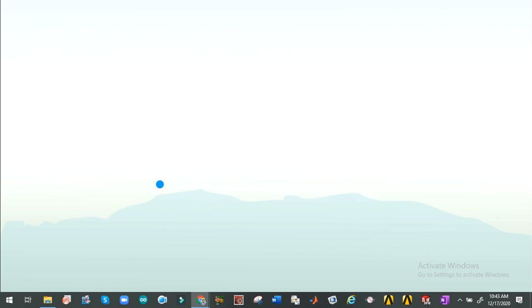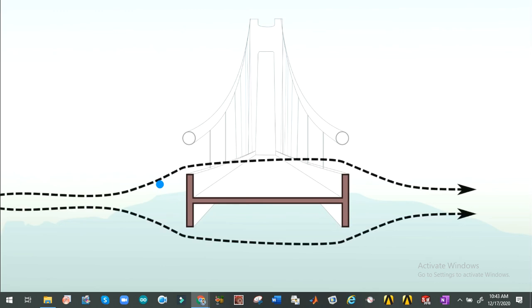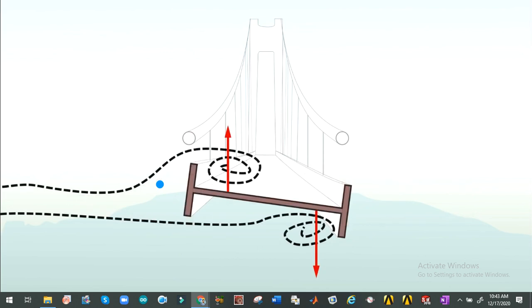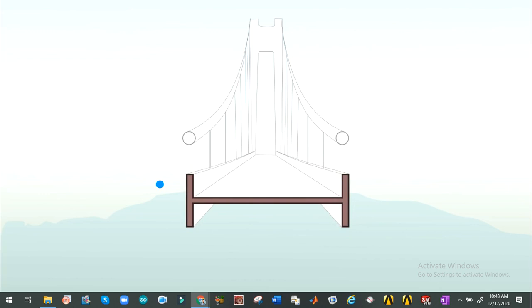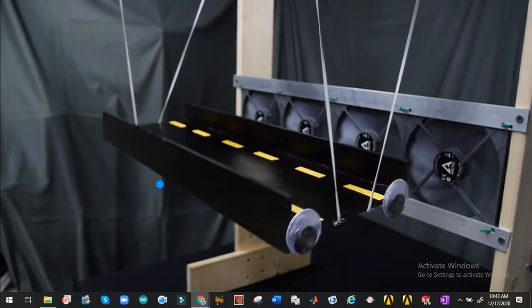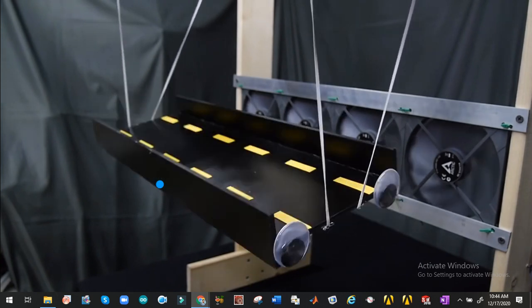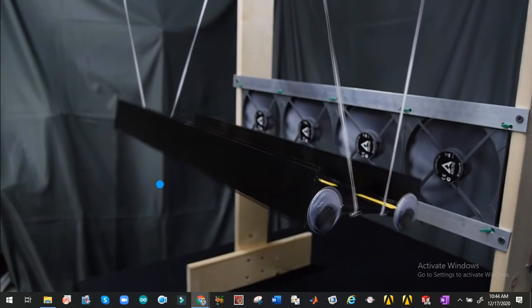Rather than a truss through which wind can flow, the shape of the Tacoma Narrows Bridge, with the large steel plates on either side, created some strange interactions with the wind. Any small amount of twist in the bridge created vortices, or areas of low pressure, in locations that actually amplified the twisting motion. Each time the bridge returned to its natural state, its momentum twisted it in the other direction, where the wind could catch it and continue the cycle. This phenomenon is called aeroelastic flutter. It's the same reason that a strap or sheet of paper vibrates in the wind. It's a completely separate mechanism than resonance from vortex shedding.